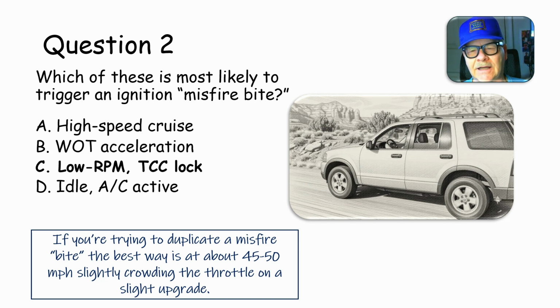That particular spark plug had a short, in other words, it was taking 20,000 volts to fire that plug, which means it had a high firing line but a short spark line. That was causing it to run out of energy whenever you were attacking it at that high RPM. The shop foreman told him, if I saw one of my guys driving anybody's car the way you're driving this one, I'd have something to say to him about it. And the guy says, well, that's the way I drive this car.